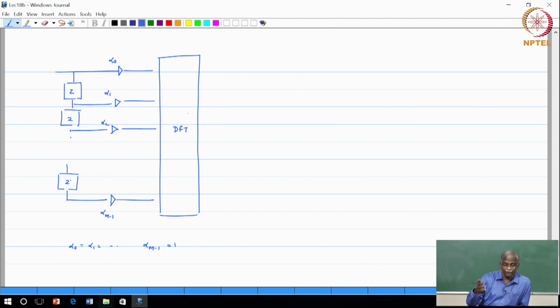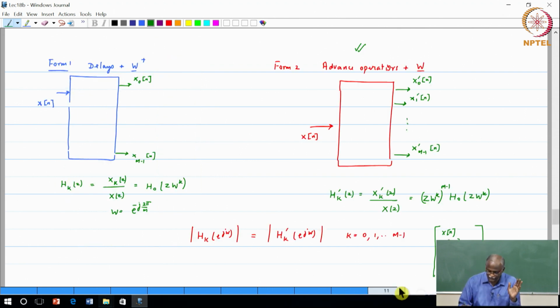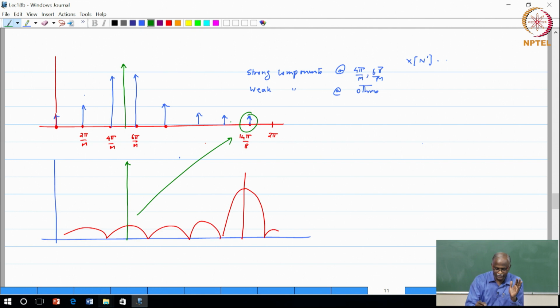Now, that is with a rectangular window. If they are not equal to 1 and they are shaped in some response, then you get the windowed DFT. So, this is what you would refer to as the windowed DFT. You solved one problem, that is, frequency components far away from where the tone lies will be substantially reduced. But I am a little bit ambitious, I want better resolution close to the signal as well: increase the window length, which means take a larger sample.